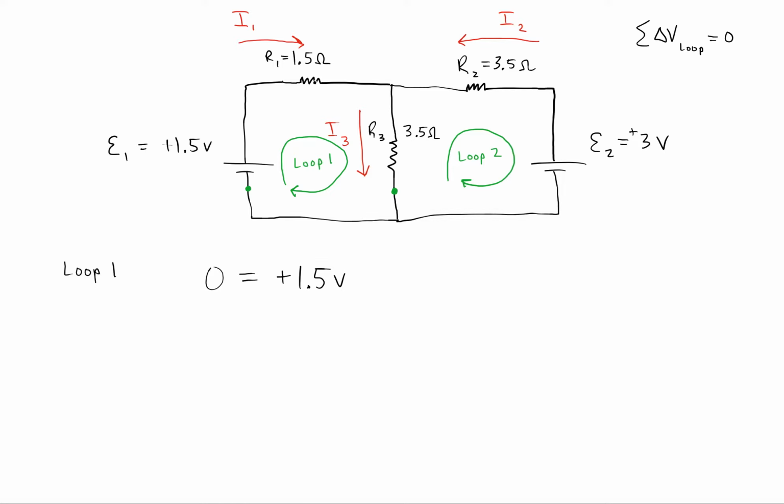Our next change though is to go through this resistor. And current flows in resistors from high potential to low. So the potential at this point in the circuit has got to be higher than the potential in this middle part. It's the only way that current could flow to the right. We start with the assumption that our guess was correct, and we base all our equations on that guess. So if our guess is correct, then there will be a drop in potential, so I want to do minus something.